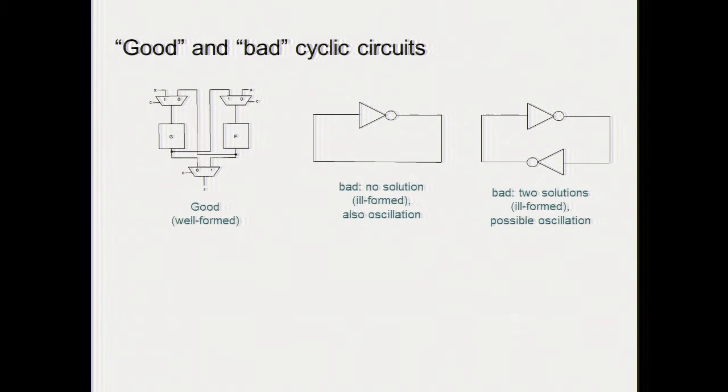So in a physical circuit, there is always a delay. And so that thing goes boom, boom, boom, boom, boom, and that is an oscillator. That's the way in which you indicate an oscillator in your circuit. But remember, it has to be a delay, and it is a physical implementation of that diagram. Because that diagram, from a logic point of view, doesn't make any sense.